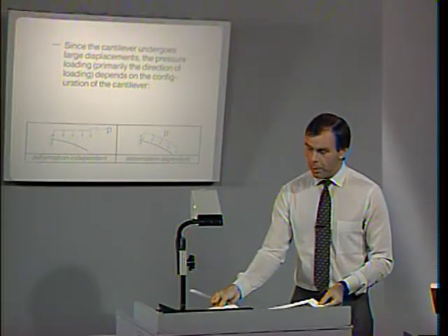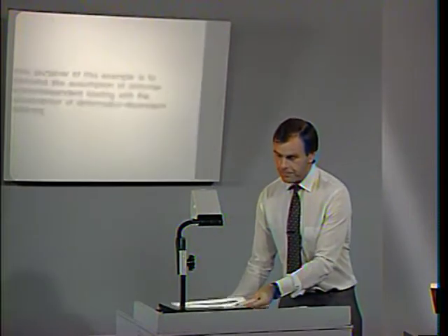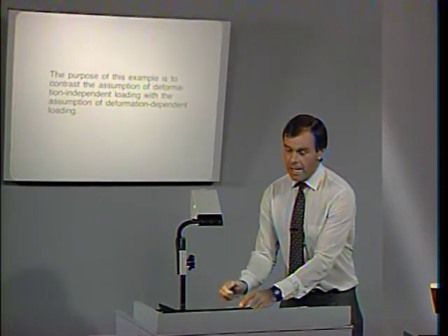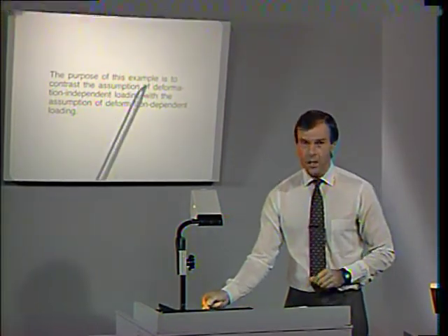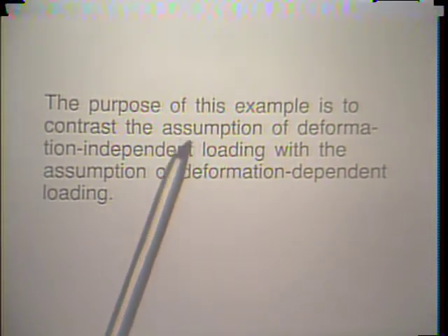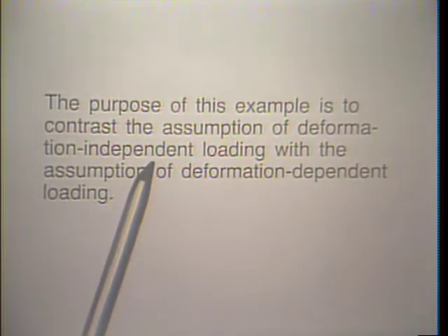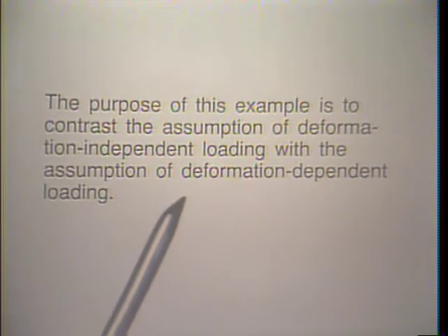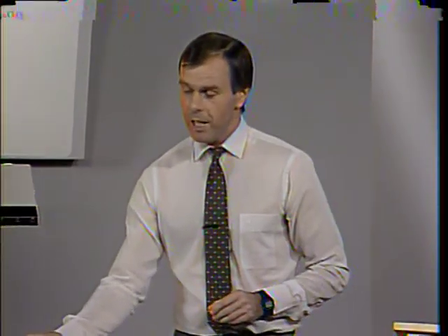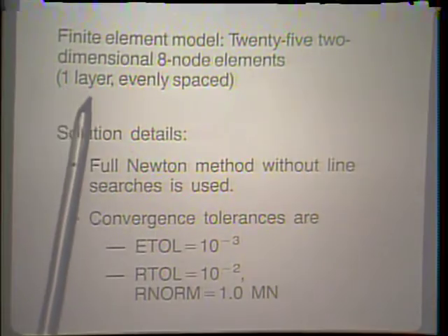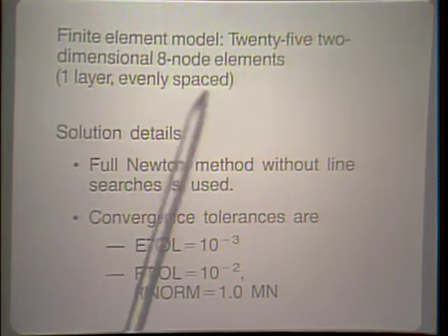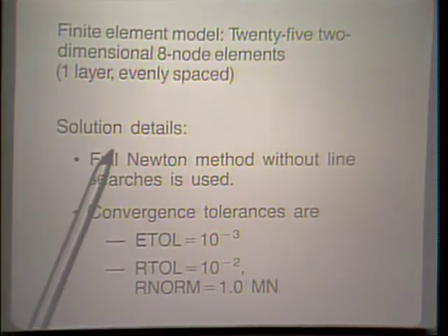Well, we performed both of these analyses, and once again the purpose here was really to contrast the assumption of deformation-independent loading with the assumption of deformation-dependent loading. The finite element model that we used consisted of 25 two-dimensional 8-node elements, one layer through the thickness, and they were evenly spaced. And here we list the solution details.